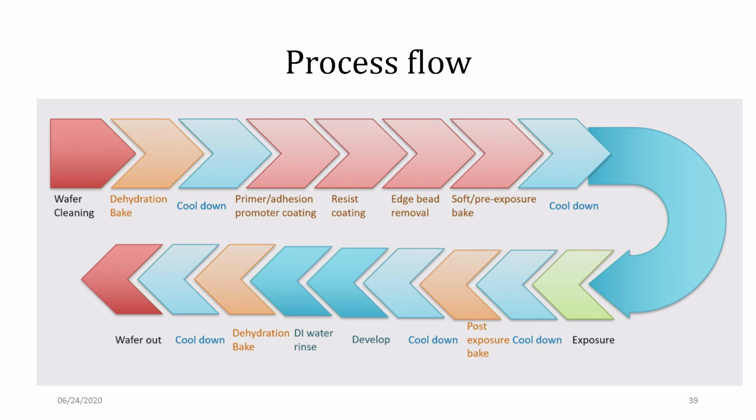And then, like developing photos, this also has to be developed. Once developed, it forms a temporary pattern on top of the substrate. Then that has to be cleaned, in the sense that the pattern has to survive and the rest has to be cleaned away, and then it goes through a dehydration bake, cool down, and the wafer is out.